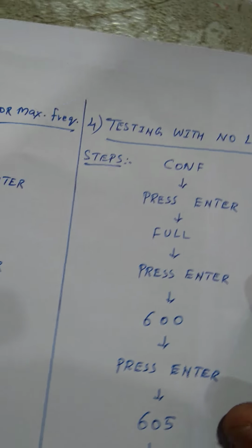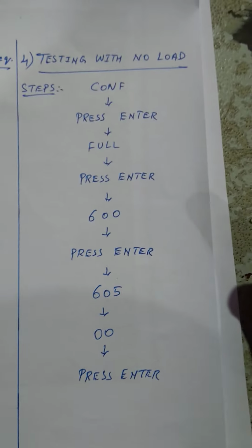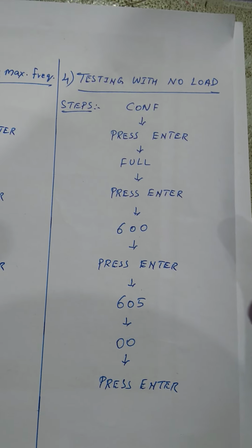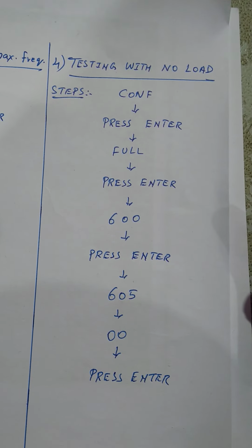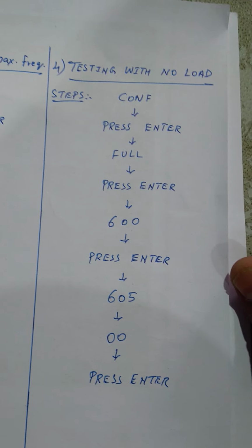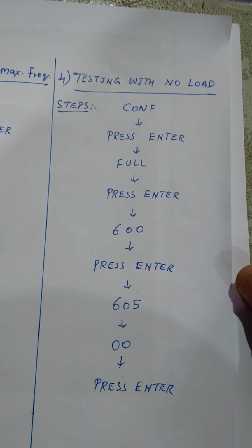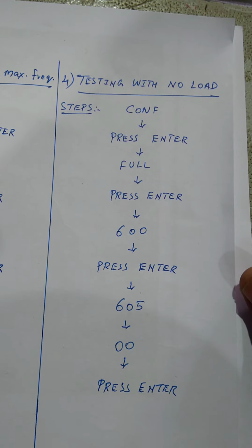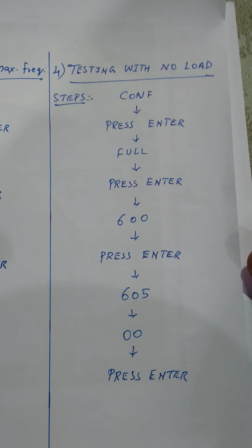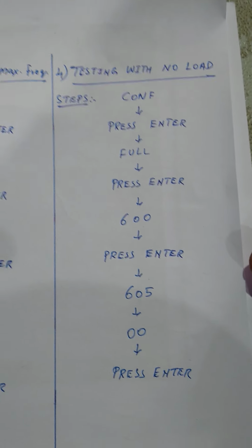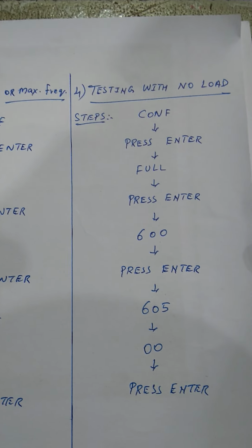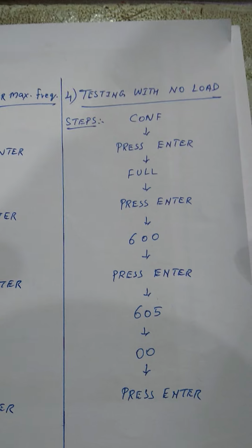Testing with no load. Okay, if you want to test the VFD with no motor or no load, then without changing this parameter, you cannot check the VFD in the run mode, because when the load is not there at the output, a motor is not connected at the output, your VFD will start as a freewheeling device for 2 seconds or 1 second, and then it will go into the trip position.